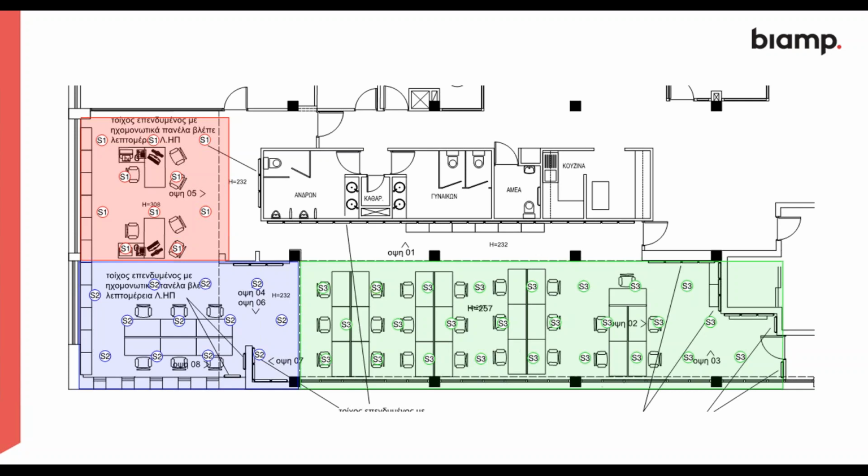Which category cable is recommended? We really tend to say Cat 5, but you can use Cat 3 or above. What happens if you exceed the maximum limits of cabling length and number of emitters? What happens there is we start to affect the impedance of the run, so we don't get the performance that we would wish. With the active emitters, if we go more than the specified amount when using it for paging and background music, it can start to fail if we have too many.